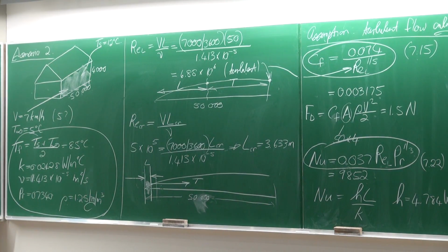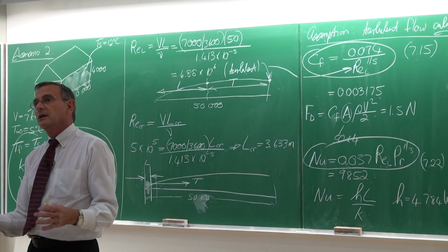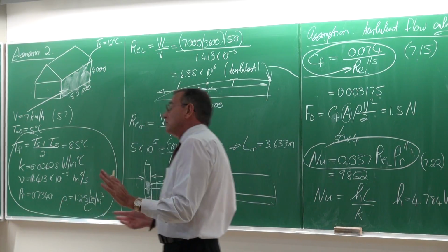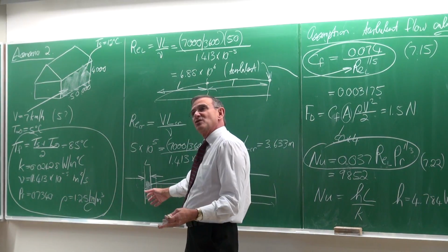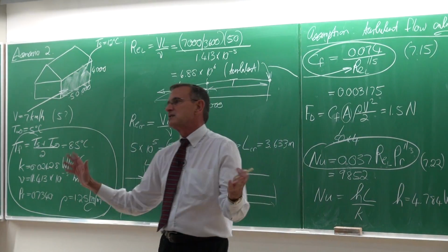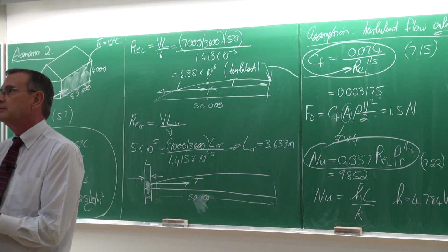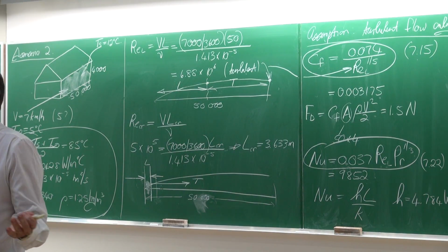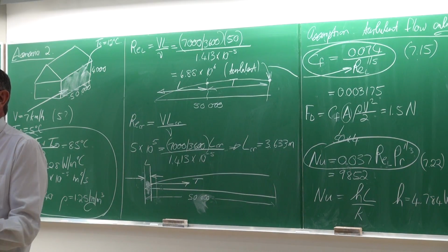Also remember, and you're going to see it right through this module, that heat transfer coefficients rarely are accurate to plus or minus 10%. In most cases, it's plus or minus 20%. Now, if you take into consideration an uncertainty of plus or minus 20%, then making this assumption in this case is an excellent assumption. But I cannot give you a good rule that you can always use. That, unfortunately, is not available.